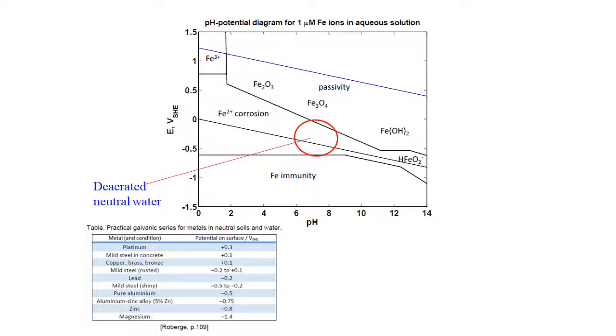Something more complicated, which we'll come back to in corrosion protection, is that very oxidizing environments with a high redox potential but neutral-ish pH can produce a passive, solid, higher oxide of iron, like the Fe3O4. And in some cases, this means that we can make iron passive against corrosion by deliberately exerting a strong oxidizing potential on it. So iron barrels, for example, could be used at neutralish pHs to store certain strong oxidizing agents because they would simply form a passive solid oxide on the iron.